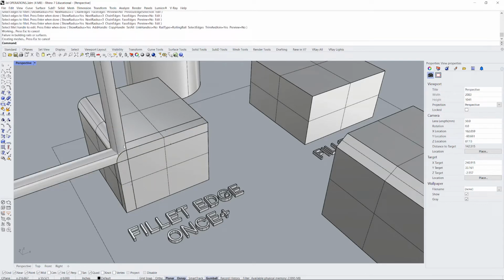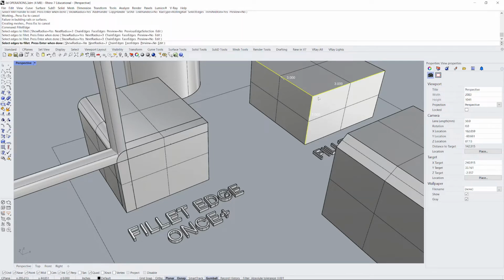That's basically because the radius that I had existing was 3 inches, and then the radius that it wants to create for these new filleted edges are also 3 inches. And so it would have to make a domed or like a quarter hemispherical corner. And it can only do that if you do it all at the same time.